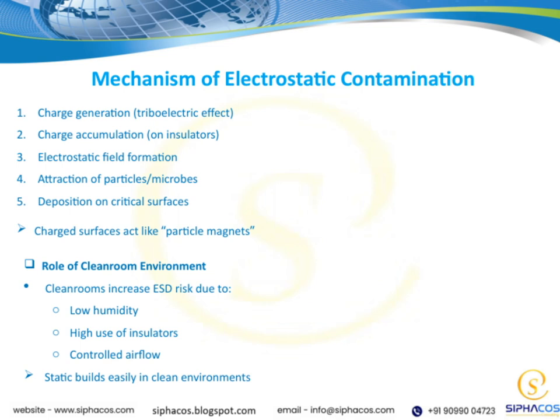Cleanrooms, while essential for maintaining a contaminant-free space, actually increase the risk of electrostatic discharge, or ESD. This is mainly because of a few key factors. First, the low humidity levels typical in cleanrooms cause the air to be dry, which makes static charges more likely to build up. Second, the high use of insulators, materials that don't easily conduct electricity, also contribute to static buildup. Third, the controlled airflow, designed to keep the environment clean, can facilitate static charge accumulation and distribution. Because of these conditions, static can build up very easily in clean environments.